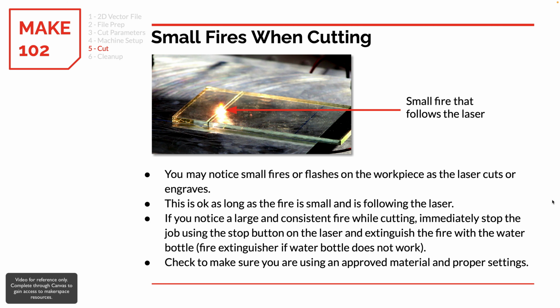While you're cutting, you may notice very small fires. These are normal. So if there is a small fire that follows the cut, so the laser beam is here, if that fire follows the laser beam and it extinguishes as the laser beam is moving, that is typically okay. However, if a small fire erupts and it does not go out, there should be small water bottles with spray nozzles near the laser.